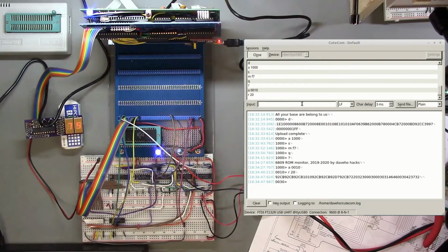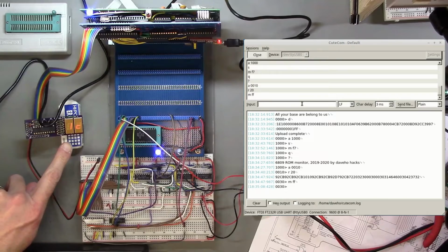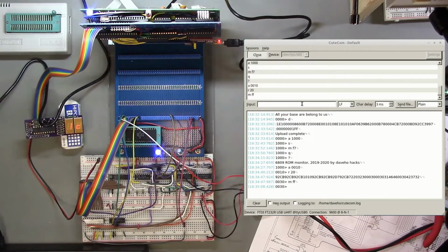So this is all great. The interrupt handler continues to execute. The monitor program continues to execute. This is pretty neat. We can do interesting things as well. For example, if we set the mask register value back to FF, notice the counter stops counting up, and essentially that's because IRQ3 is now blocked by the interrupt controller because we've blocked off that bit in the mask register.